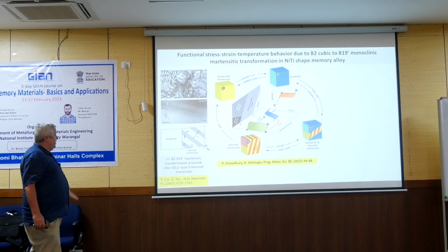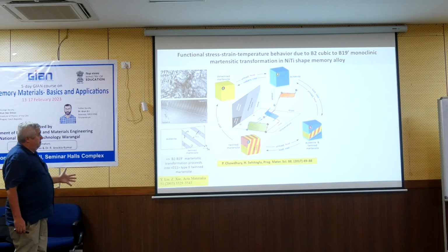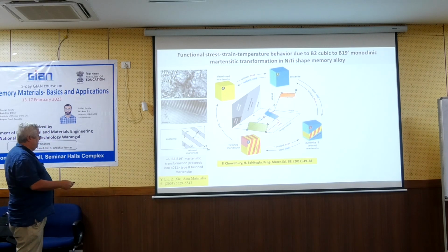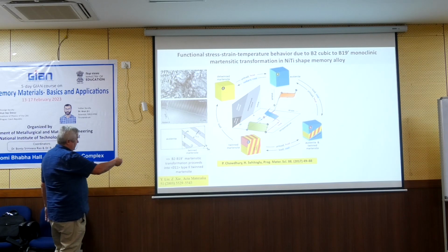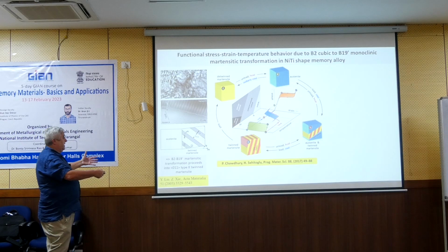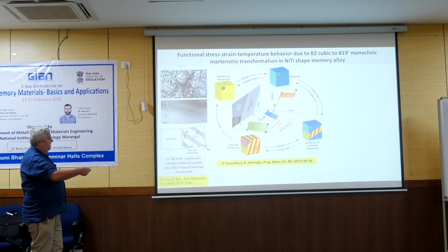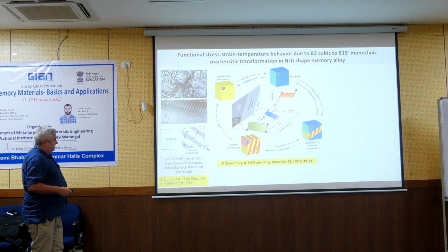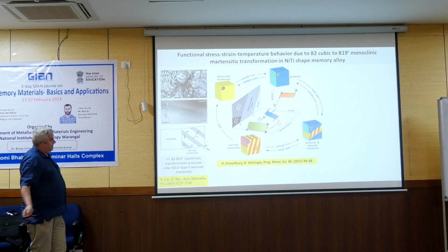So this is still some understanding of the current state-of-the-art knowledge. If you look into the literature, the state-of-the-art is, as I discussed a little before, the austenite to martensite transformation into type 2 twin laminates. Even people in micromechanics modeling of martensitic transformation use this scheme, but as I said before, this doesn't apply for nanocrystalline alloys.